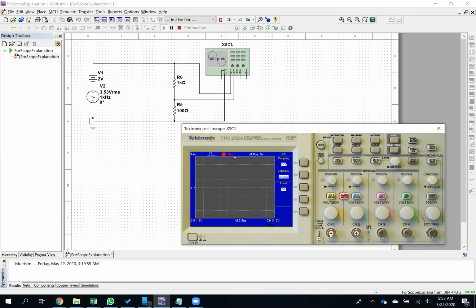I see the settings for channel 1. I see that I'm on DC coupling. Let me draw on the screen. DC coupling right here, which I want. Also note that my volts per division is set to coarse, which I want, because it means when I'm changing this value, it's changing by standard increments, like 1, 2, 5, 10.